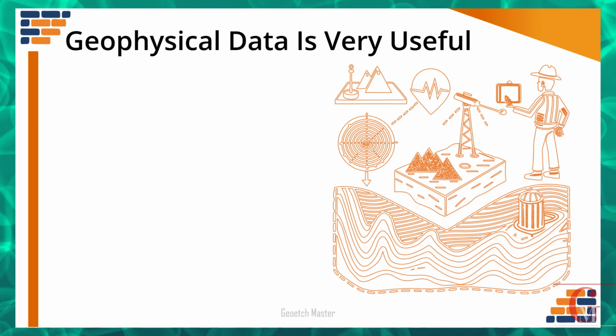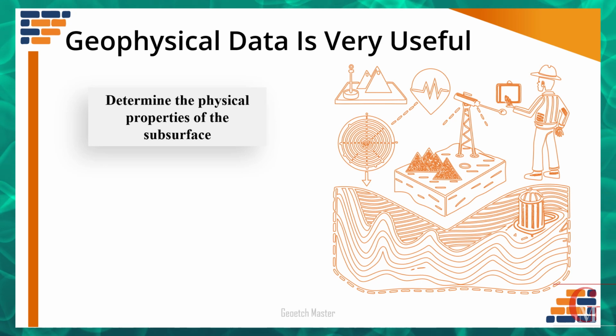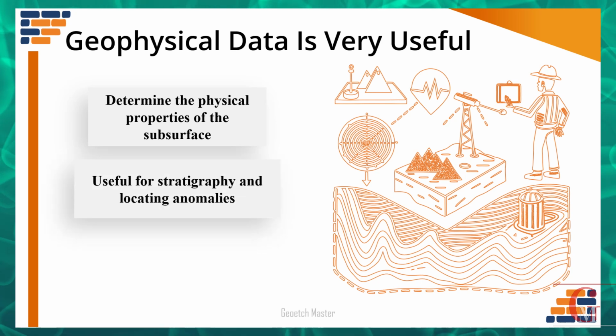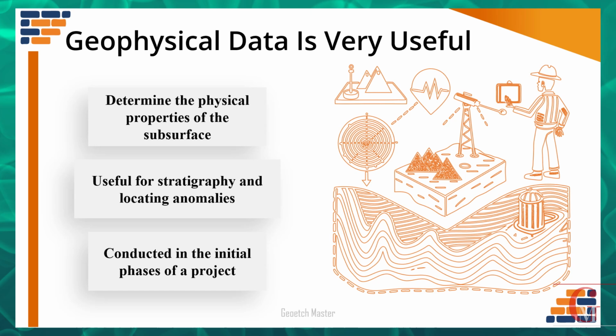Geophysics is very useful for determining the physical properties of the subsurface, including stratigraphy and the location and size of potential anomalies. Geophysical testing is usually conducted in initial phases of a project because, as we saw earlier, this helps optimize the locations of subsequent borings and soundings.